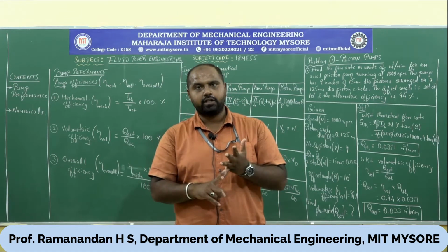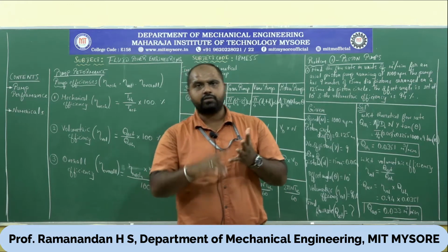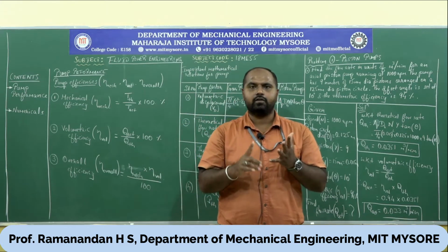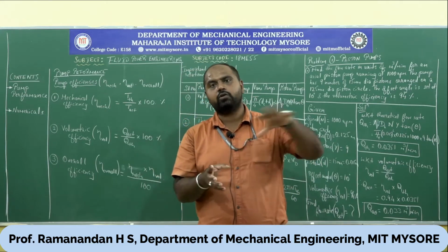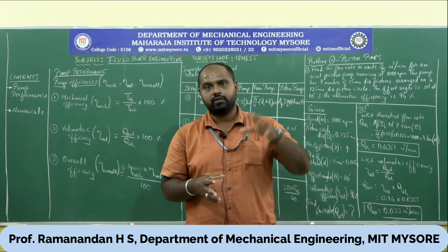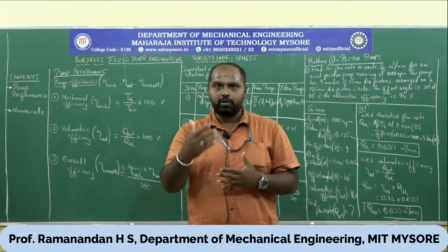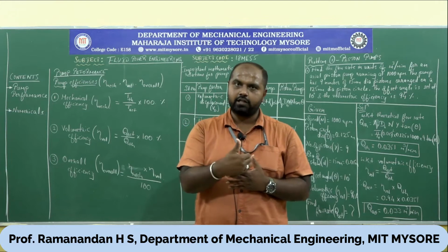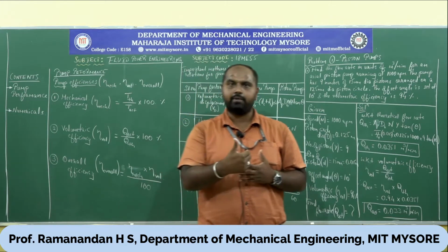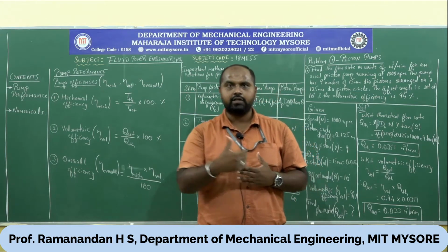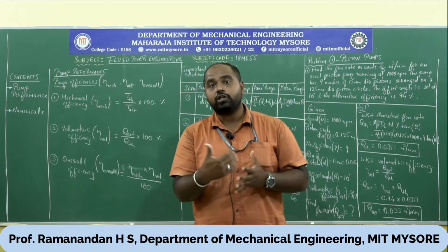So material is nothing but diameter, dimensions, diameter or width or eccentricity, or area of the material. Manufacturing process is how do you achieve this dimension of the pump. How do you manufacture the gear with a tolerance, with a pitch circle diameter, or if it is a vane, diameter of the vane, width of the vane, eccentricity between the rotor and the cam ring. So all these play a vital role.